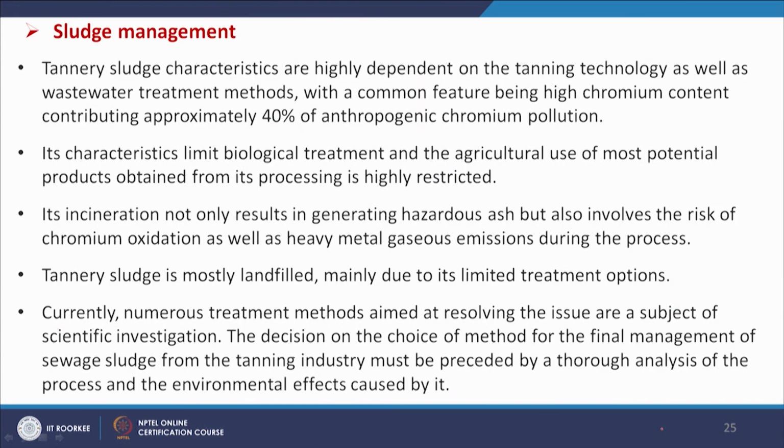Now, sludge management. The tannery sludge characteristics are highly dependent on the tanning technology as well as wastewater treatment methods, with a common feature being high chromium content contributing approximately 40% of anthropogenic chromium pollution, and its characteristics limit biological treatment. The agricultural use of most potential products obtained from its processing is highly restricted because of high chromium concentration.